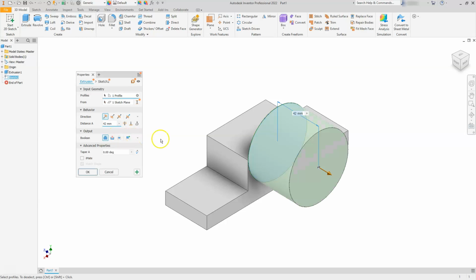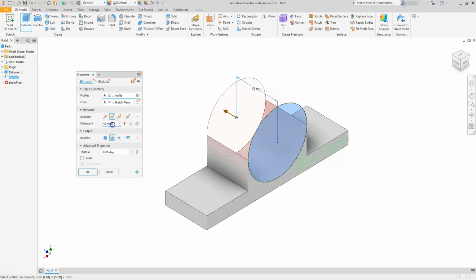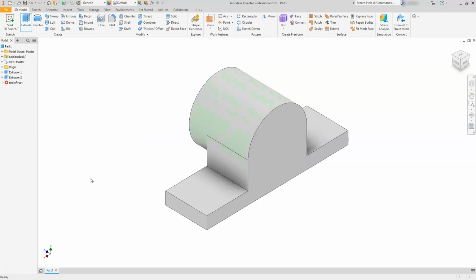And this time you'll see that it will totally light up that whole entire sketch for me. So that's a huge benefit of using the construction option. I'm going to turn that to go the other direction. I'm going to give it a distance of 60. And now I have to tell it, instead of subtracting from my shape, I want that to actually be a part of it. So I'm going to tell it to join it. And then I'll select OK.